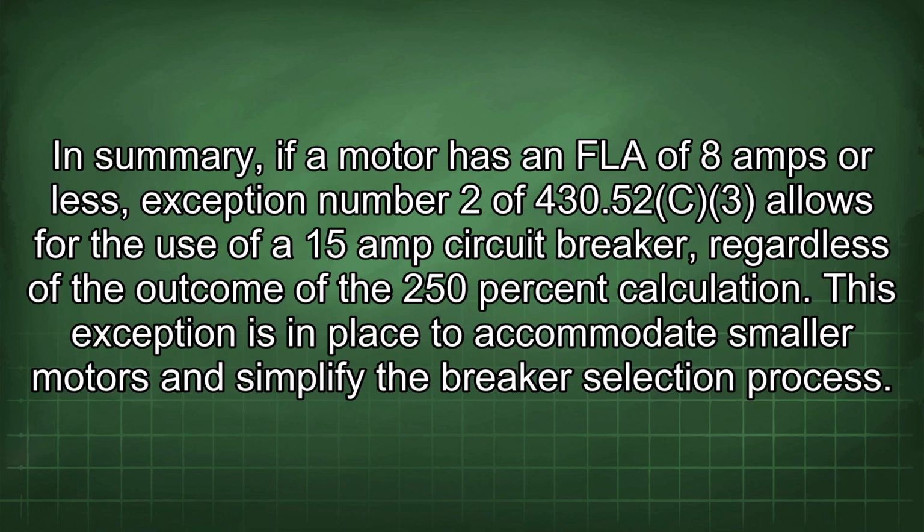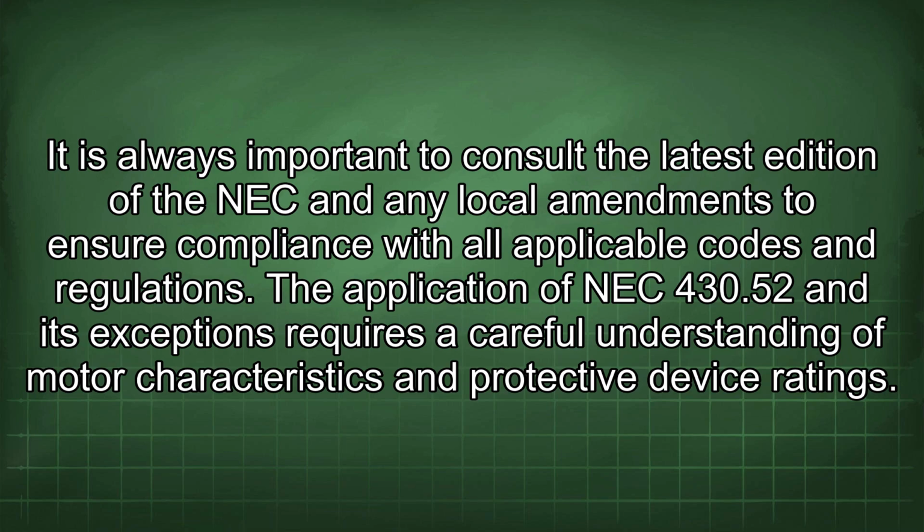In summary, if a motor has an FLA of 8 amps or less, Exception No. 2 of 430.52(C)(3) allows for the use of a 15 amp circuit breaker, regardless of the outcome of the 250% calculation. This exception is in place to accommodate smaller motors and simplify the breaker selection process. It is always important to consult the latest edition of the NEC and any local amendments to ensure compliance with all applicable codes and regulations.